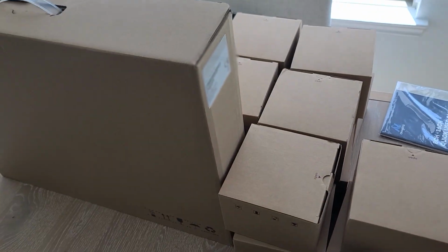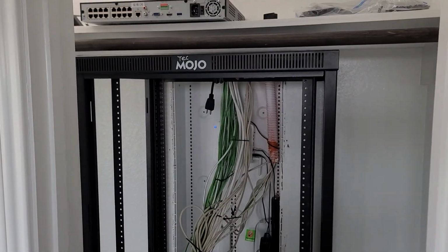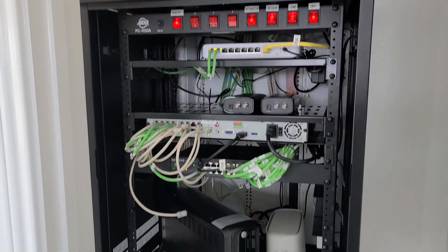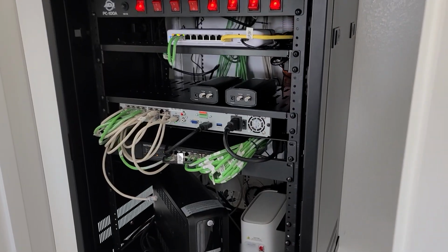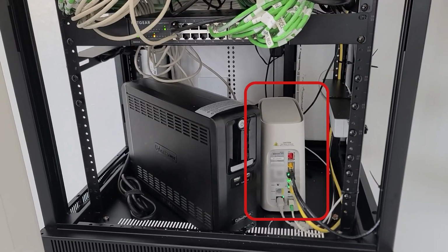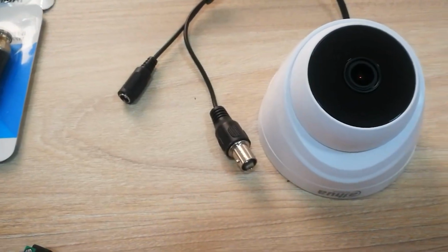These systems have the enormous advantage that they work in such a way that their wiring converges at the location where we are going to install our recording unit, DVR, or in this case, NVR, Network Video Recorder. This has another great advantage of being able to electrically back up the system with a UPS. Here we can see a preview of how this system ended up. This allows us not only to operate with batteries, but also to stay connected to the internet even after a power failure. Very important.